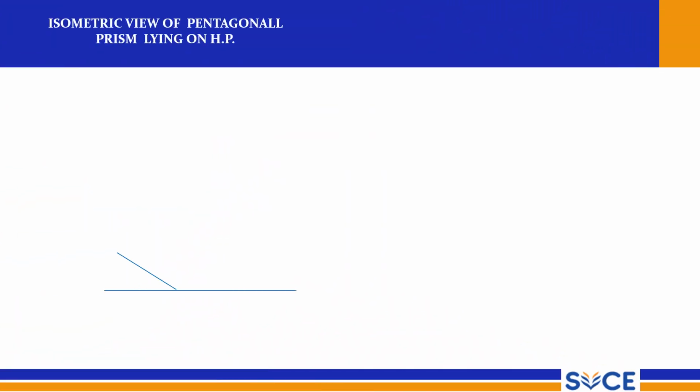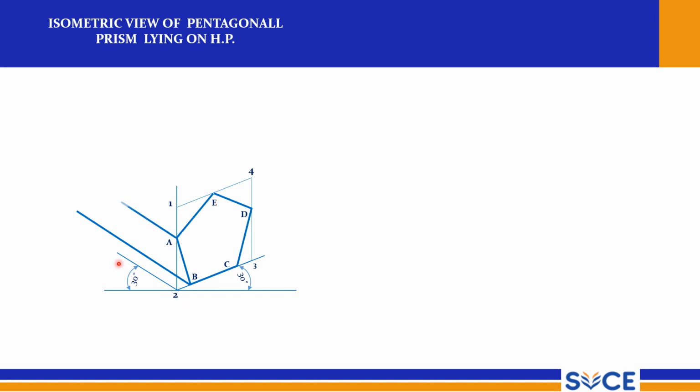And this is the pentagonal pyramid, right? Pentagonal pyramid lying on HP. It is the 30-30 plane that is used to draw the front view, and that is the true shape of the pentagon. And now this is prism. From each and every corner parallel to the 30-degree line, you draw the given height. Now it should be drawn, and this should be connected, and this is your hexagonal prism.